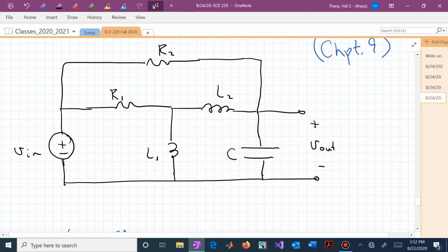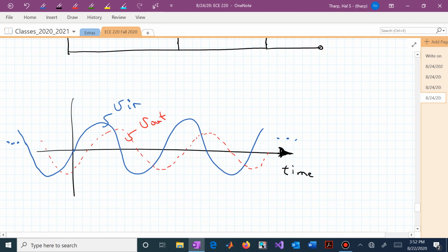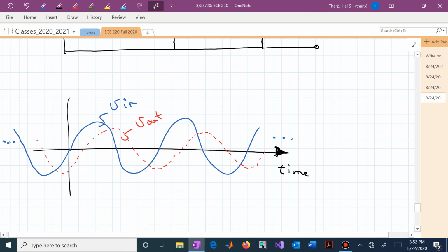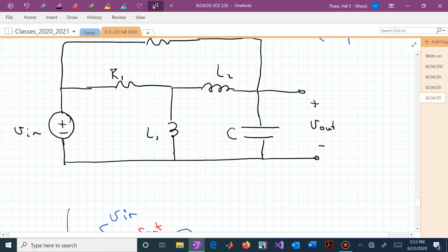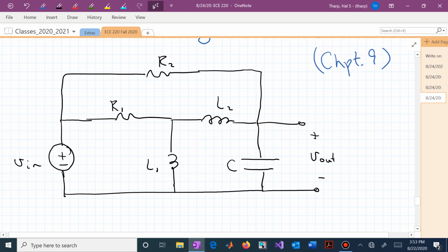I said, oh, let's do differential equations. Now we have 10th order circuits or 10 energy storage devices. Oh, well, what we will learn is we can actually still do the algebra, or convert this analysis into algebra, by using complex numbers. So if we now understand how to convert sinusoids into complex phasor descriptions, we will then convert these inductors and capacitors into complex impedances, which are generalizations of resistors. Those impedances now are dependent on frequency.